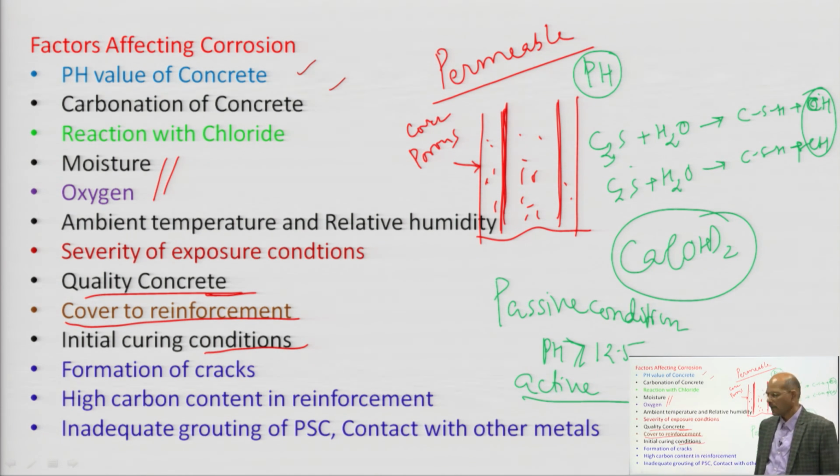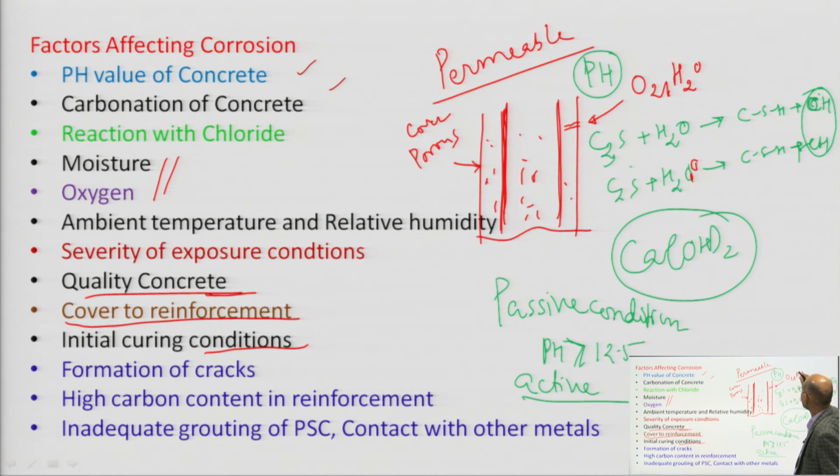Then formation of cracks. If there are cracks in the structure, let us say there are cracks here, through these cracks what will happen? Ingress of oxygen, water, carbon dioxide, chloride, sulphate, etc. will be more. Okay.